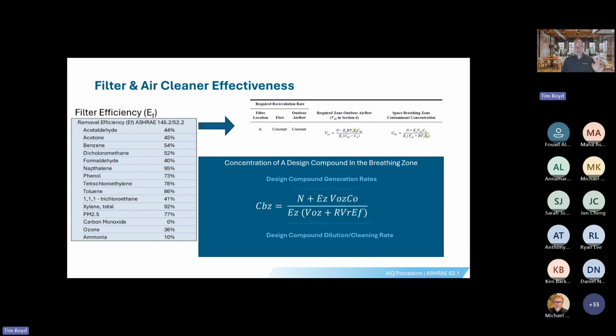And so that's why you can get really good savings doing this approach. I'll give you a good example. Traditionally, in most traditional places, especially high occupancy public assembly spaces, you can cut your outdoor air by about 50% with the right air cleaner. And your cost savings could be somewhere between $1 for every $1 you invest, you're saving about $8 off of that project in first cost. That's the value of this type of benefit for so many different reasons.